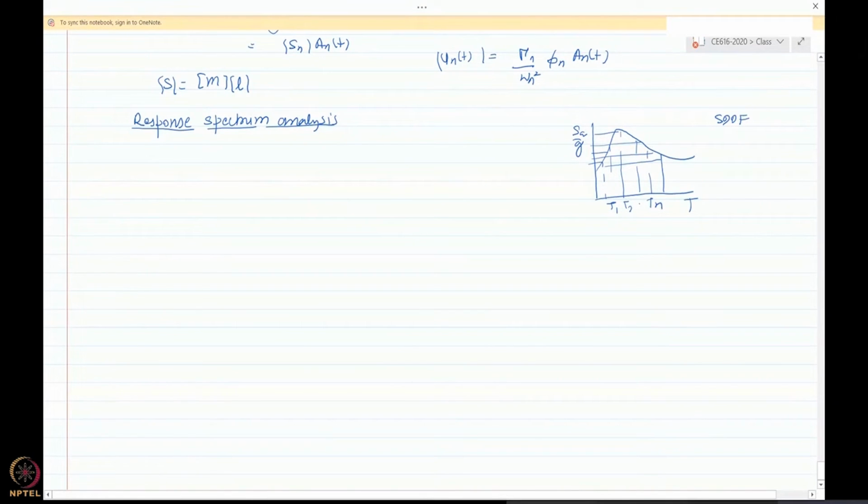But they will also occur at different times. And if An is given or displacement is given, doesn't matter. Always remember this expression: An equals omega n square times Dn. This is a good approximation if damping is smaller than 20%.